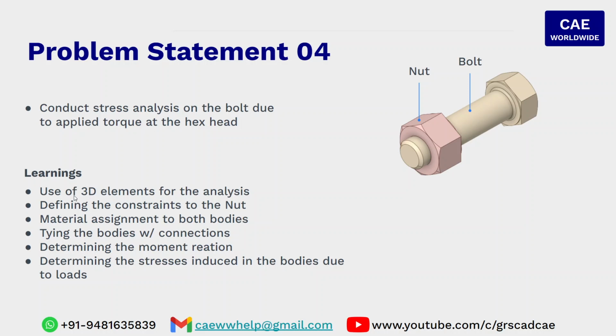Learnings: use of 3D elements for the analysis. Since the geometry is complex, we cannot simplify to 2D or 1D. It has to be considered a 3D analysis itself. Generally, standard parts like fasteners are not analyzed. This analysis we are still conducting for learning purposes.